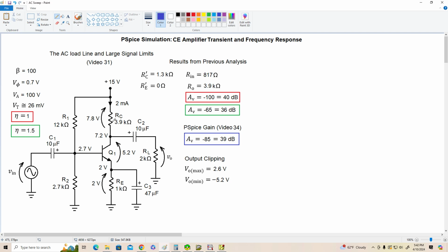All right, so if we start at the input side, what we've got is our voltage source driving the input resistance of the amplifier, Rin, through coupling capacitor C1, and this forms a high-pass filter. What we want to do is ensure that the corner frequency of this filter is at least as low as the lowest frequency we want to amplify. The corner frequency for this filter, FC at the base, is equal to 1 over 2 pi Rin times C1.